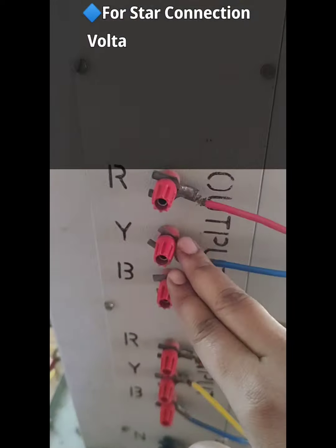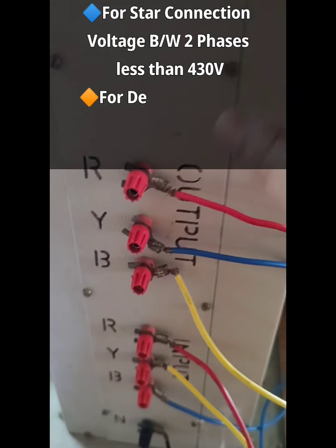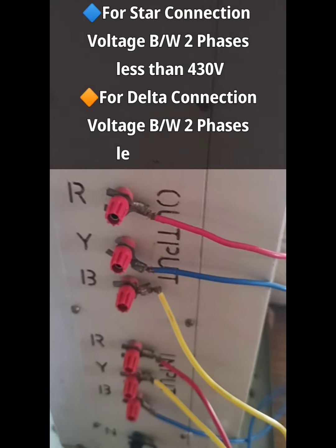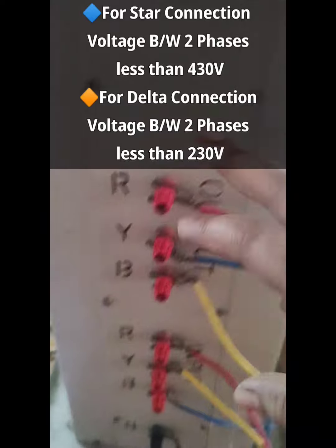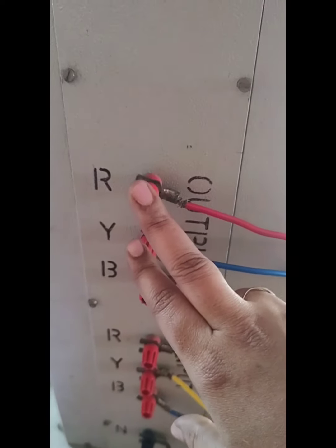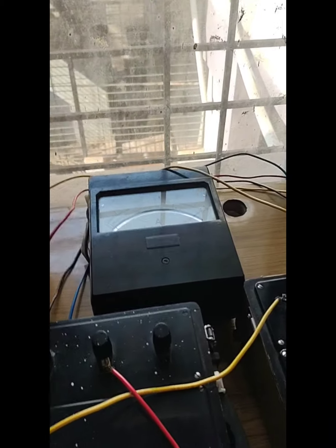For delta, we should keep the voltage between two phases below 230. Once you check the procedure, for star connection we keep below 430, and for delta connection below 230 volts between two phases. First we should set the voltage, then apply the load, and then take the reading of current.